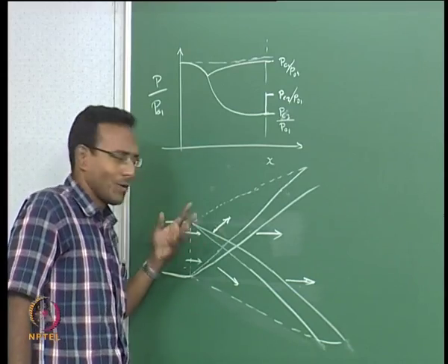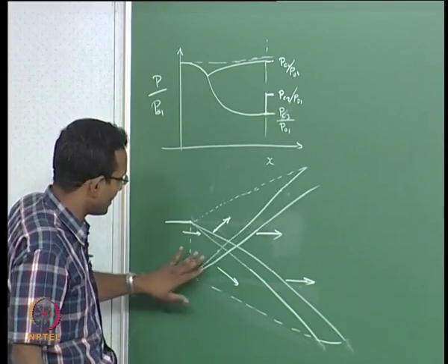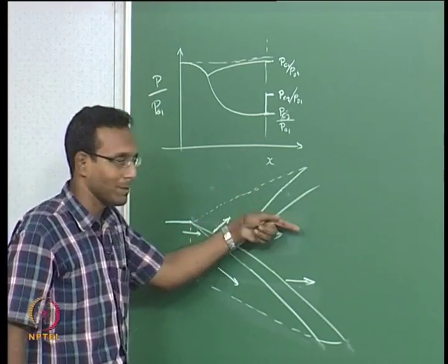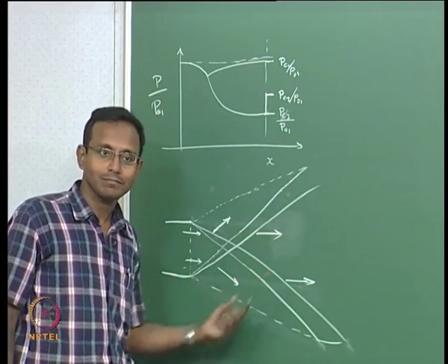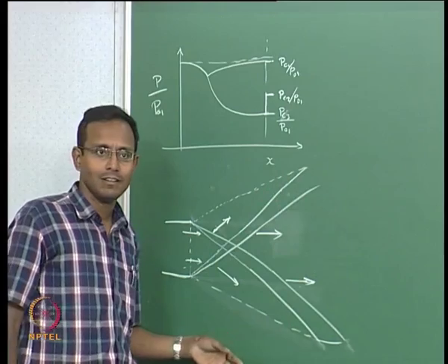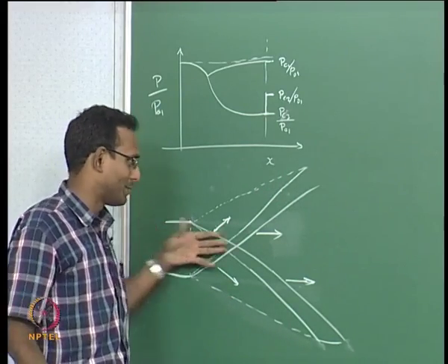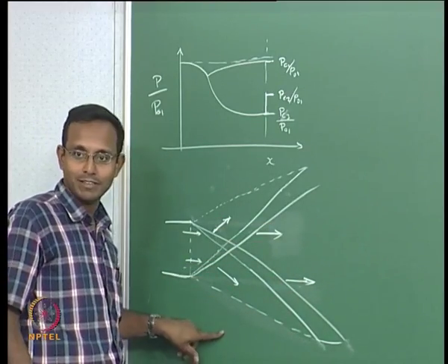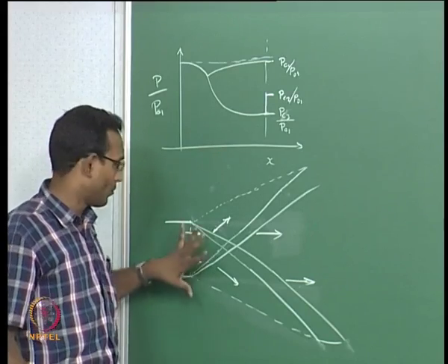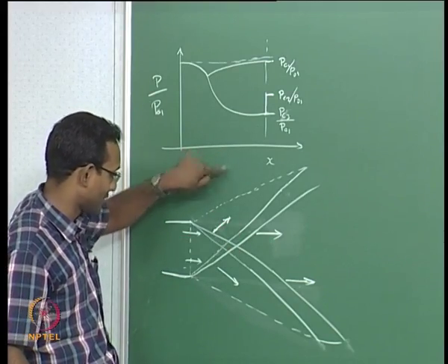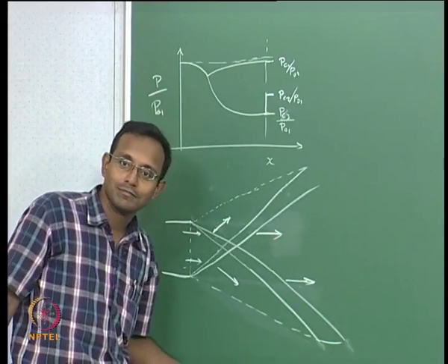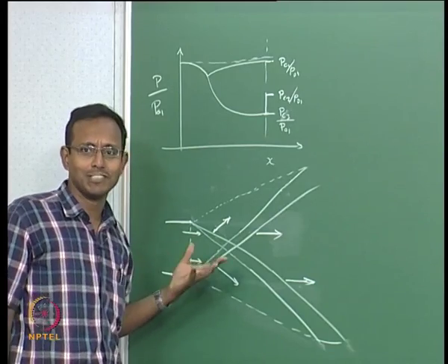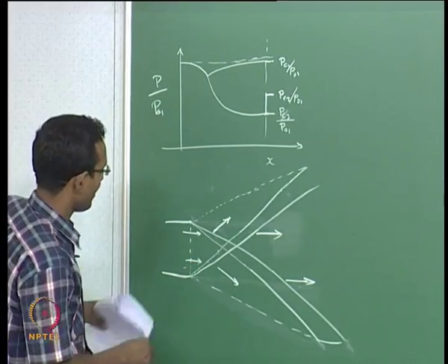If I think about a very complex problem, then I can have this pressure different from this pressure and these expansions will not be symmetric, which means this will bend it by some angle, this will not bend it back by the same angle, it will bend it by some other angle, and the final fluid will have some net direction. And you can always expect that because now the jet will not go symmetric, it is going to be tilted to the down if this pressure is more than this pressure. Why? There is a pressure difference across this fluid element. Overall fluid element that is coming out is seeing that this pressure is higher than this, it is going to accelerate down net, right. That is one more way of looking at it. It has to do that eventually. Just think simple logic, it works most of the times.